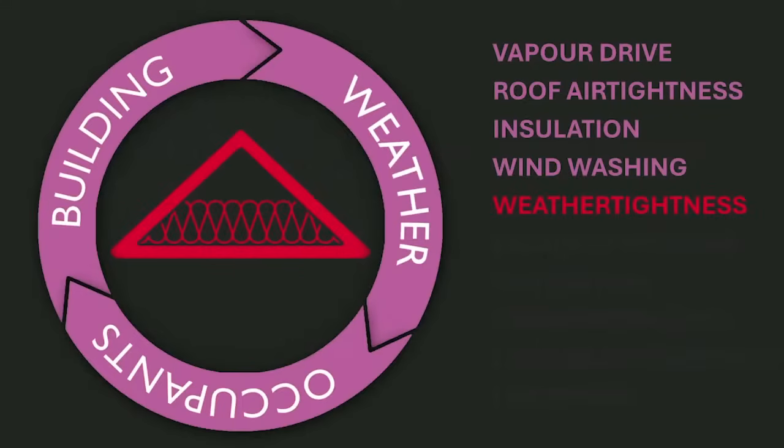Ensuring all parts of the roof structure can properly resist wind loads without damage is also important. As with many aspects of roof design, this may have a knock-on effect on other parts of the specification. For example, if a particularly exposed location requires the use of additional wind bracing or sarking boards, or necessitates changes to the specified outer covering, this may require additional or different condensation control measures.